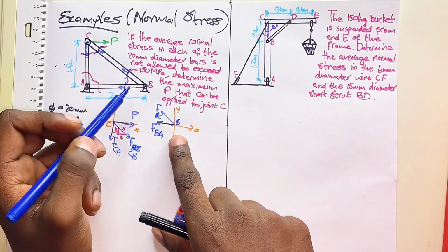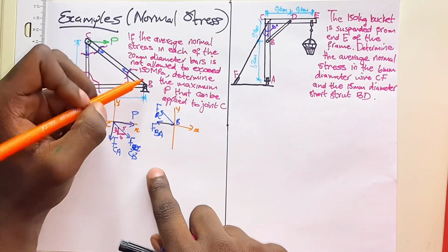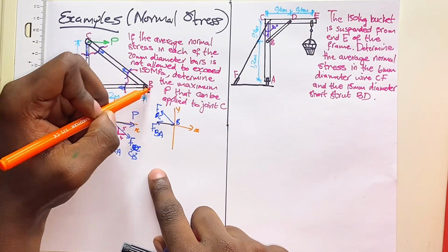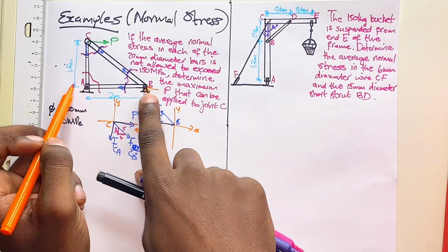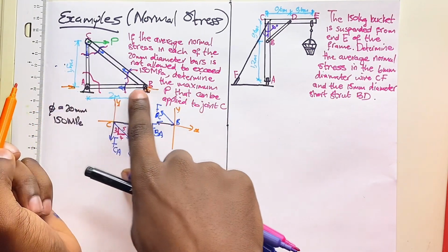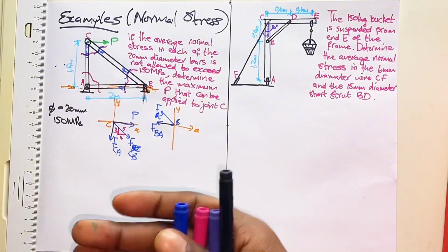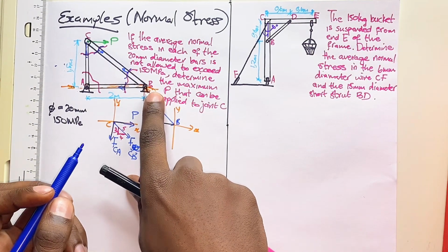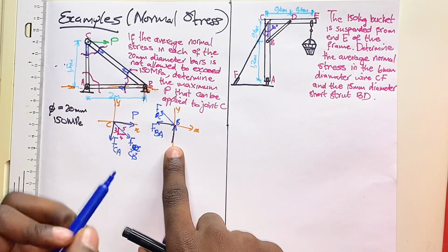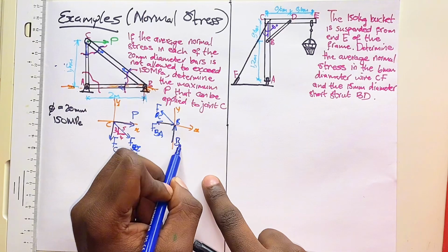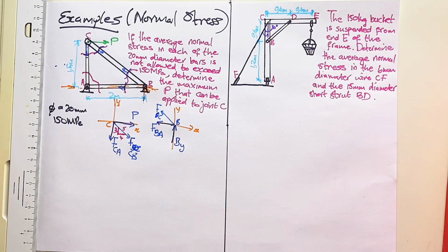And those are the only forces acting there. You'll also have the reactions that are being experienced by the joint. But since you do not have any uniaxial forces acting in this axis between A and B, you will not have the X component of the reaction. We'll only have the Y component, and it's acting upwards. We'll call that BY for the reaction of the pin in the Y axis.